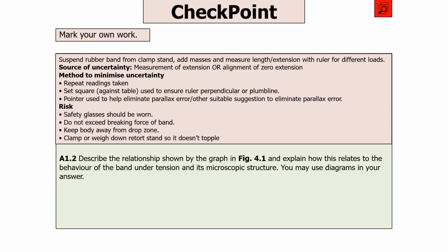Now the risk in this experiment is you should have safety glasses on, make sure you don't exceed the breaking force of the band so that it snaps, keep your body away from the drop zone in case it does snap, and make sure that the clamp is weighed down so that it doesn't topple over.